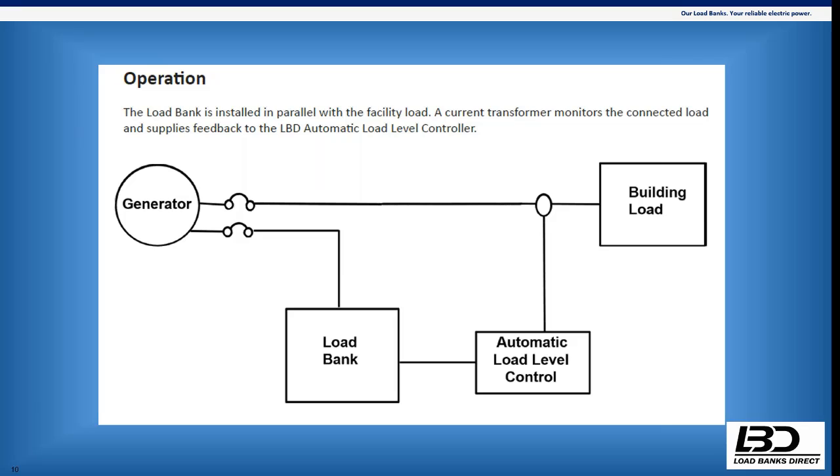So if that relay were to lose power because any of those safeties or the blower operation was compromised, that relay dumps all the load, so everything goes open. Like the person that asked the question said, does everything fail open? It fails open, so it shuts down.